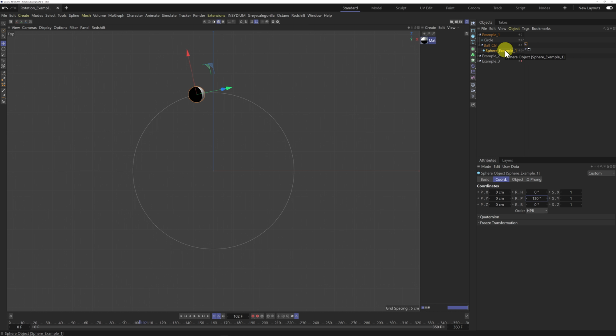animates around. Now what we're going to do is we're going to work out the rotational value of our ball so that it rotates seamlessly around this spline here. So we need to work out the frequency of this ball moving around this spline. So the speed of everything is set by our keyframes here. So we can set our keyframes down to 0 to 180 if we want to. But the rotational frequency of the ball is going to be exactly the same. So we know the ball rotates at 360 degrees. We need to find out the distance of one rotation there.